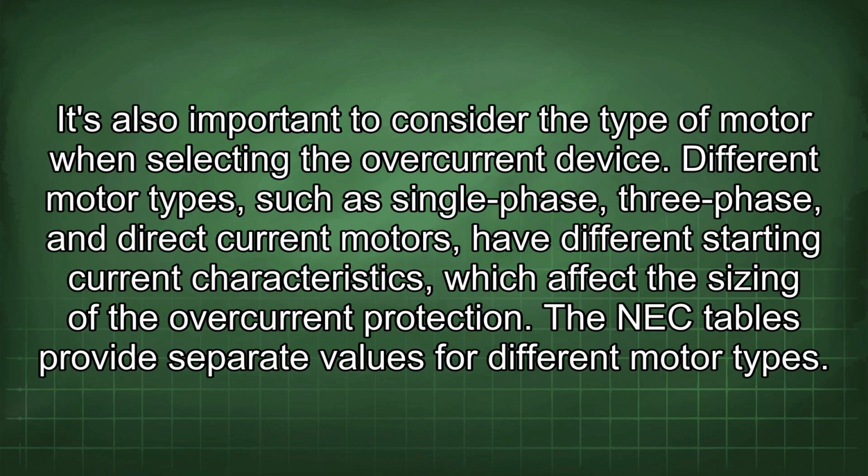It's also important to consider the type of motor when selecting the overcurrent device. Different motor types, such as single-phase, three-phase, and direct current motors, have different starting current characteristics which affect the sizing of the overcurrent protection. The NEC tables provide separate values for different motor types.